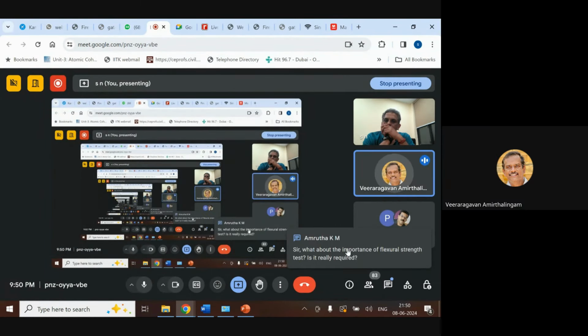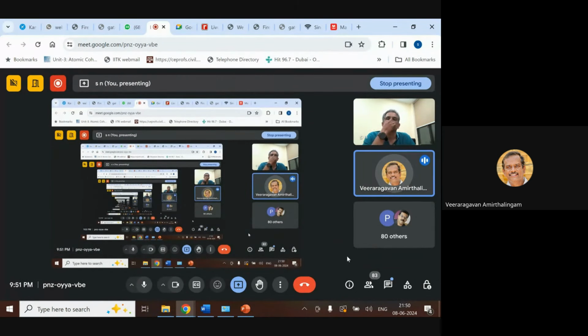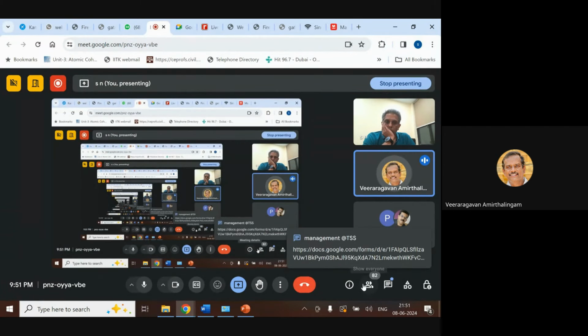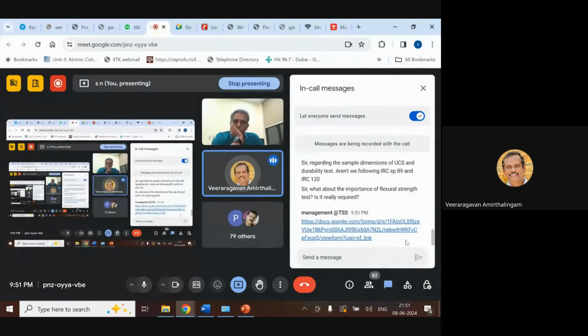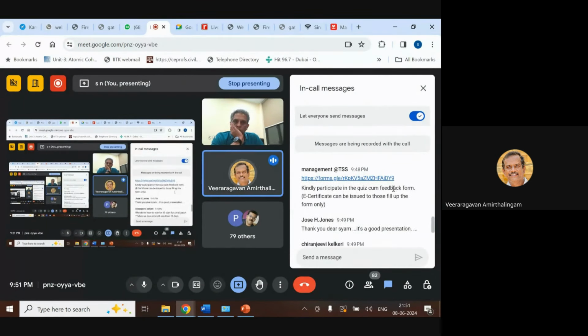This has been time tested around the world. There's nothing new. Definitely, what we are now talking about is reusing the material that's already there so that we can reduce the virgin aggregate consumption. Any stabilized, improved material is likely to perform better than a deteriorated pavement. That's why we are recommending an FDR.